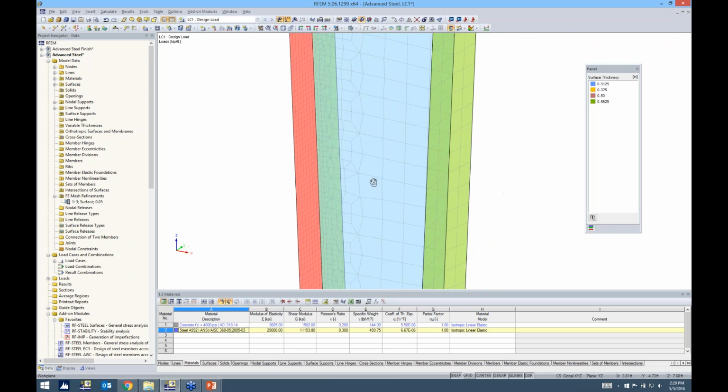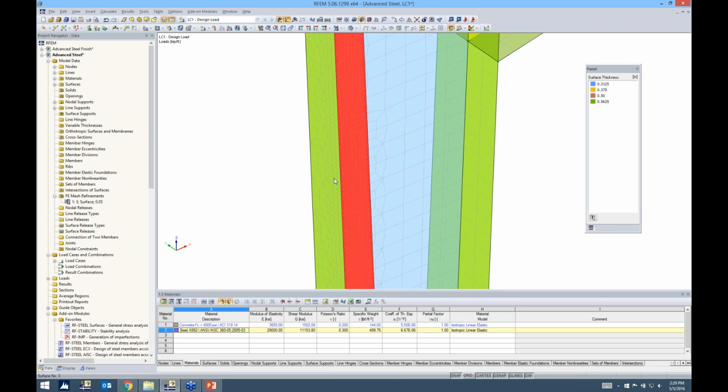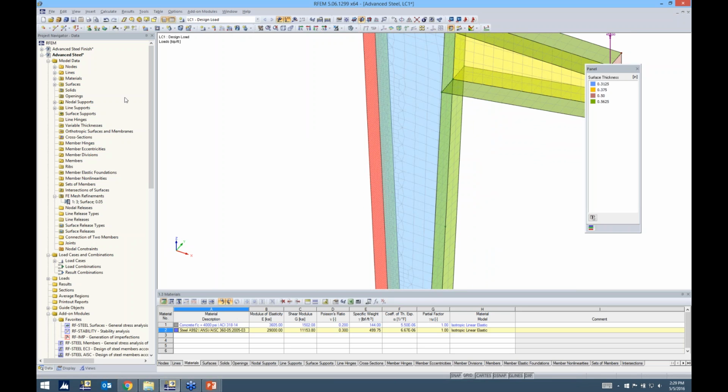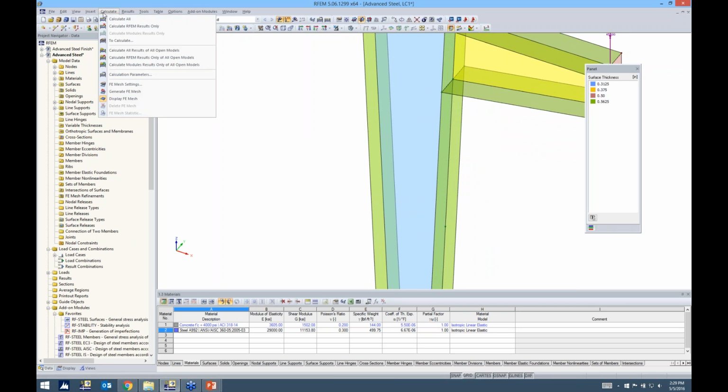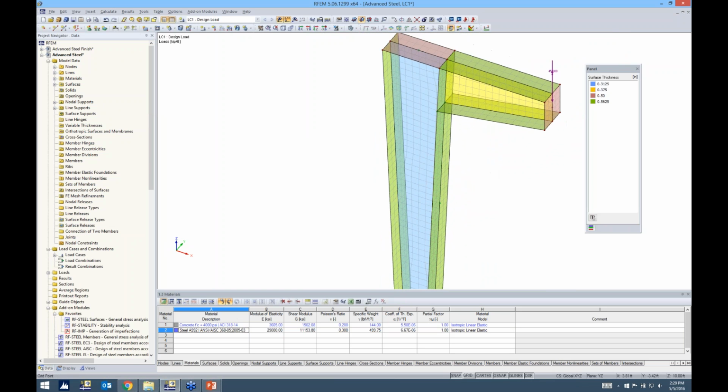So that's quite nice, and you'll notice too that it transitions back into the global setting of 0.2 feet for both adjacent surfaces. For our case today, I'm going to go ahead and leave it as the 2 elements across the width, and that's just for solution purposes, just to speed things up a little bit. So I can go ahead and generate my FE mesh.